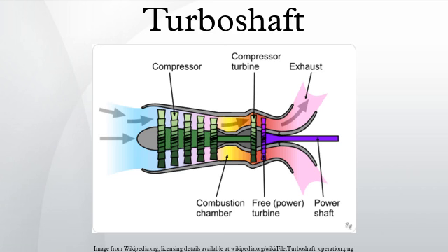The general layout of a turboshaft is similar to that of a turboprop. The main difference is a turboprop is structurally designed to support the loads created by a rotating propeller, as the propeller is not attached to anything but the engine itself. In contrast, turboshaft engines usually drive a transmission which is not structurally attached to the engine. The transmission is attached to the vehicle structure and supports the loads created instead of the engine. In practice, though, many of the same engines are built in both turboprop and turboshaft versions, with only minor differences.